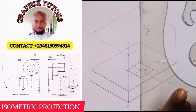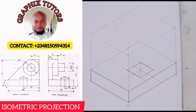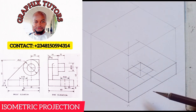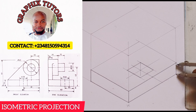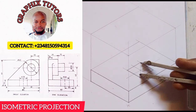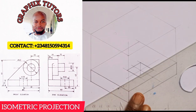Then I'll bring this down. Can you see that line? I bring it down. The depth, because it's going through, that's why the hidden line is coming from the top to the bottom. So if I place it here, this is thickness of 15. I'll come here and I'm going to mark 15 here. Can you see where I mark this 15? That will now help me to close it up.